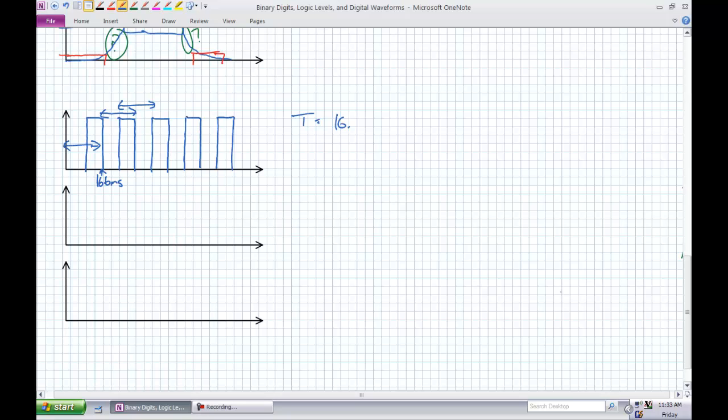So if the period is 16.6 milliseconds, what is the frequency? Go ahead, and this is what I'm talking about, actively participating in these lectures. Pause this and do the calculations, because guess what I'm going to do? I'm going to do the calculations right here and show you what you should be coming up with. Okay, so my frequency is 1 over T. How many cycles per second? If it takes me 16.67 milliseconds to complete one cycle, I should get roughly 60 hertz.